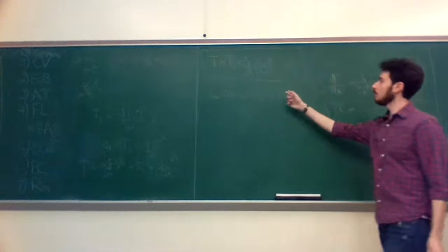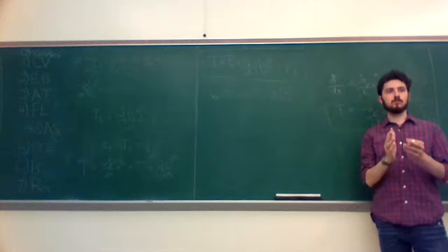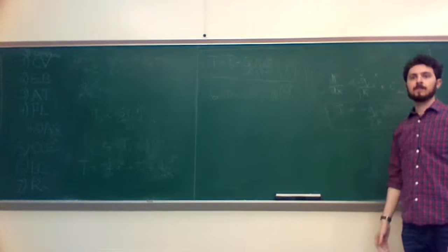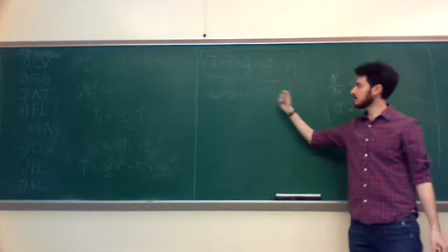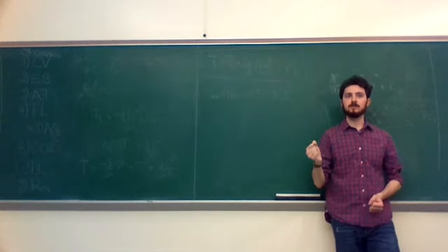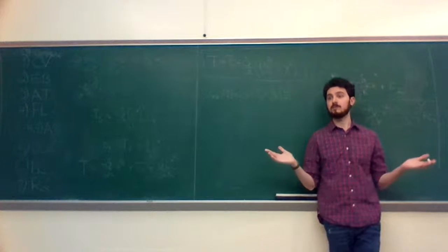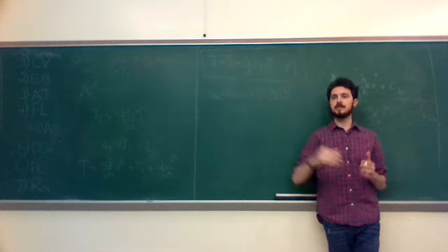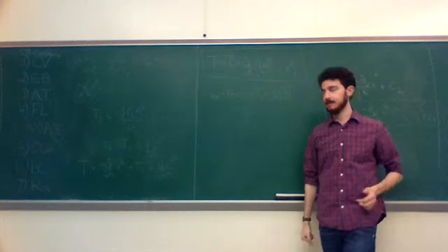And what drives this temperature? If you want a hotter temperature at the core, what do you do to the size of the slab? Make it bigger, smaller? Holding everything else equal. Bigger, yeah. As you increase the thickness of the slab, L, the temperature at the core increases quadratically. So that is your strongest signal that this slab is essentially self-insulating, right? If you double its size, you're going to quadruple the added temperature over the surface temperature at the core.